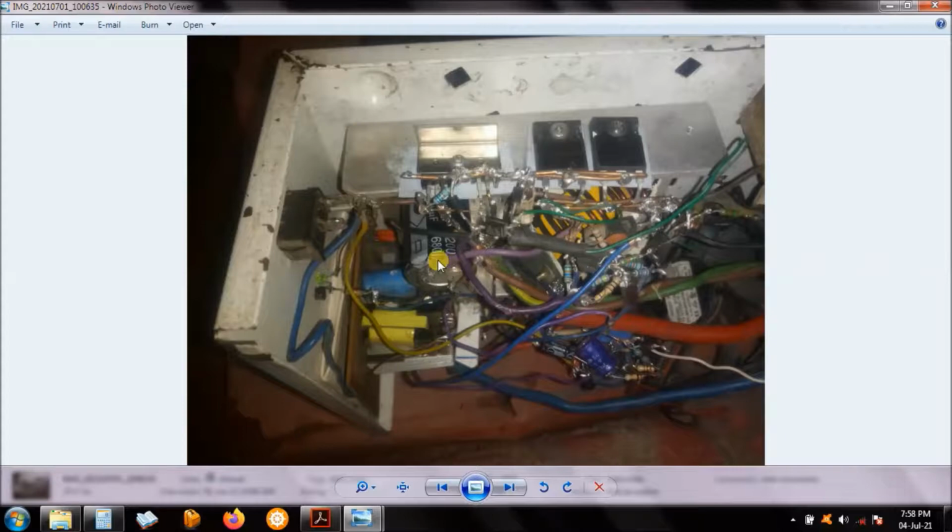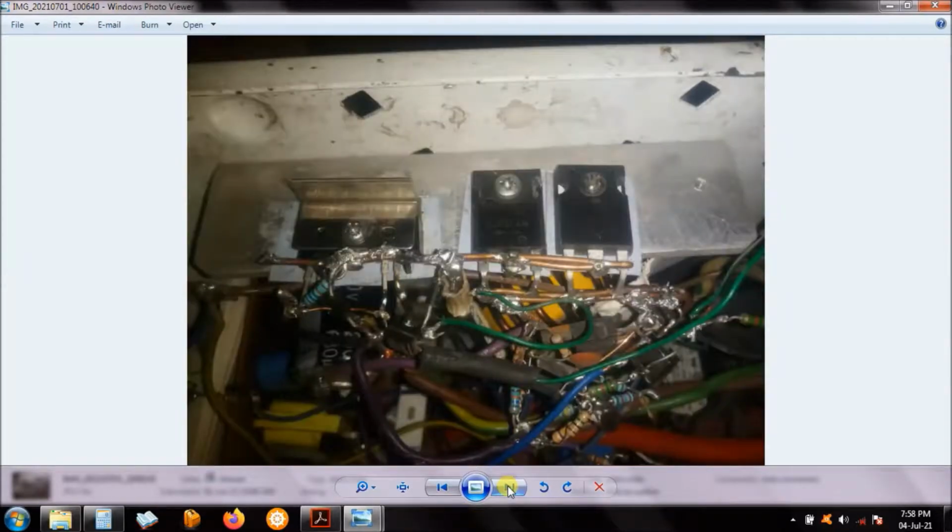The input capacitor, and here is the power supply for driving the MOSFETs, the high side power supply to drive these MOSFETs. And then here is the sleep circuit. Here is the MPPT circuit. There is a 555 timer there under. Right, let me try to get to another. Yeah, the Schottky diode. That's a 30 amp. Well, you can see here. I think that's 30 amp, 40 volts, I think, according to that. Right, the MPPT circuit is here.